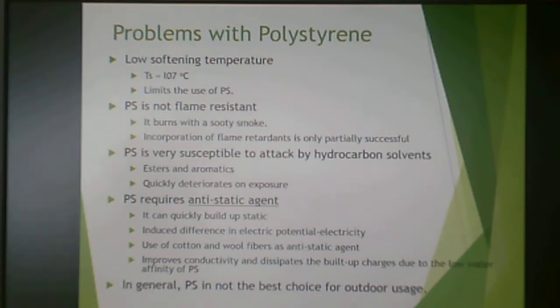It has a low softening temperature of 107, and so this limits the use of polystyrene. It's good for processing, but if it softens at 100 degrees Celsius, it will do so in your part as well, so you're not going to have structural integrity of your part.